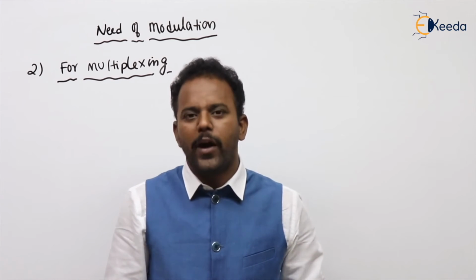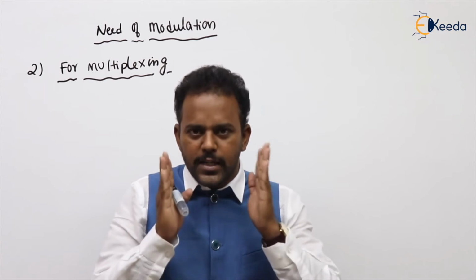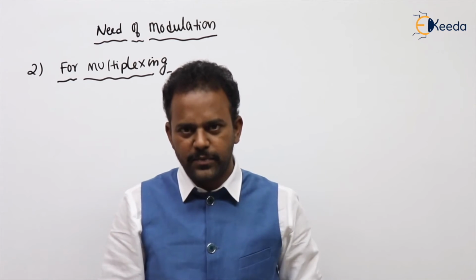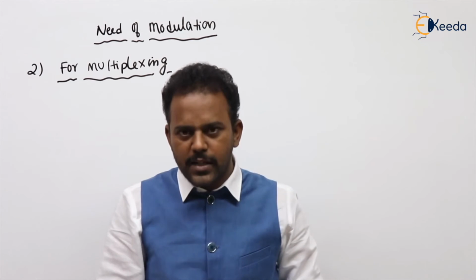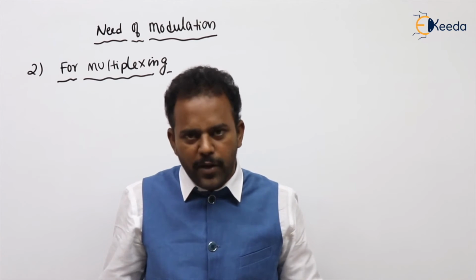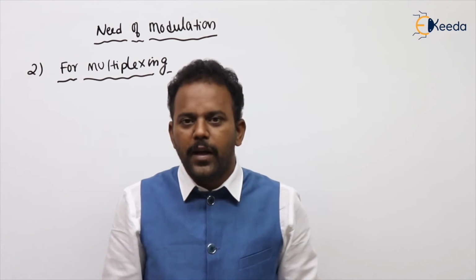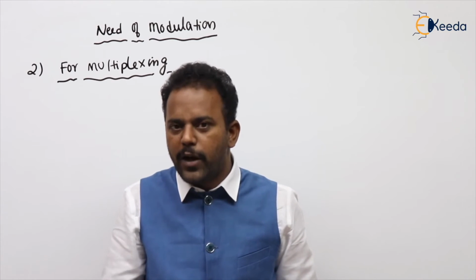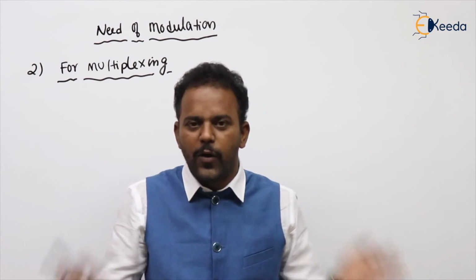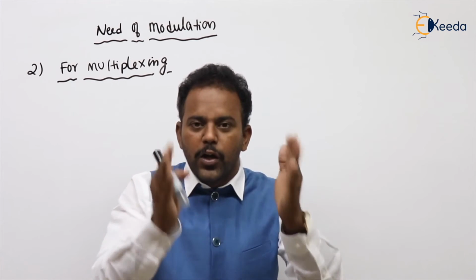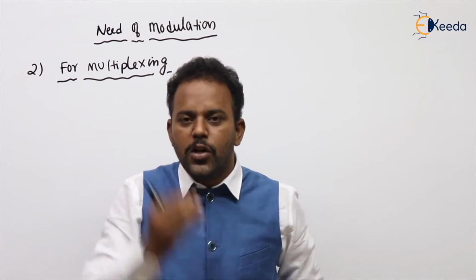Why, sir? Why is modulation a must? I can take a simple example. Now you are listening to the communication class, at the same time you are listening to the signals class, and at the same time the mathematics class. Because all three subjects are taught by faculty, all are the same voice signal or maybe video. Voice signal means 300 to 3.4K, video means 0 to 4.5. All are in the same frequency range, so all will interfere. You will get a mixing of these three subjects, so you never get any single mark in the GATE exam.